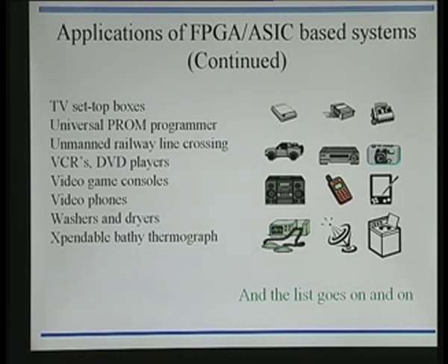And the last one I have listed here, maybe around 61 or 62, I will leave it to you to count, is the expendable bathythermograph, which I have myself handled quite a few decades back, and I heard that it is still in vogue. This is to sense the temperature of the ocean without stopping the ship as such. Normally it uses a thermistor of around 4.7 K at the tip of a spool, with twin bonded wire, and it can be launched from the rear end of the ship, and when the probe touches the water, the recording commences.